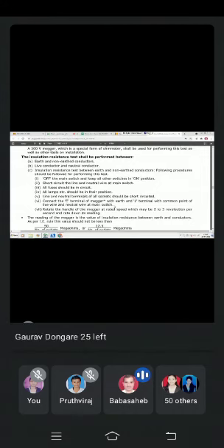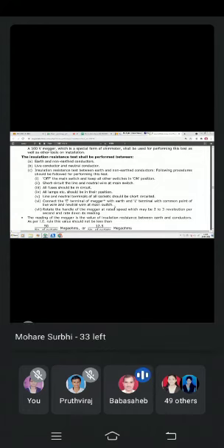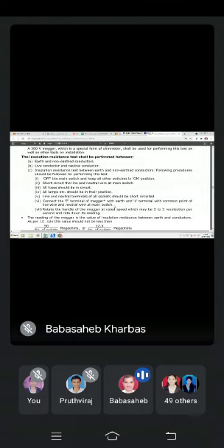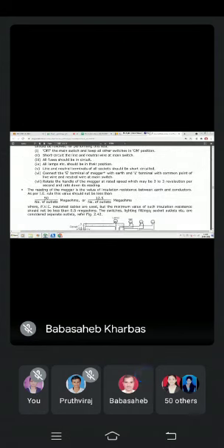Okay. Line and neutral terminals of all sockets should be short circuited. Then connect terminal E to the measure, L to the line, and the line terminal to the common point of live wire and neutral wire at the main switch. Then you have to rotate the handle of the measure such that